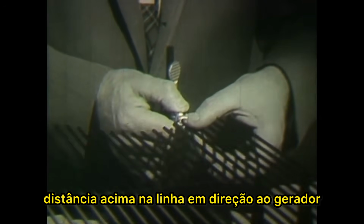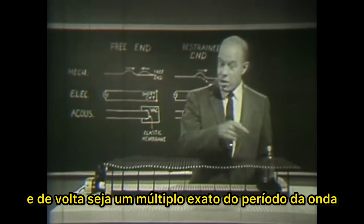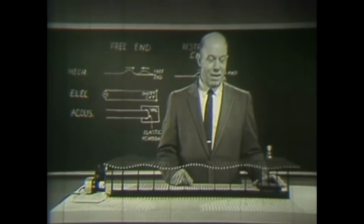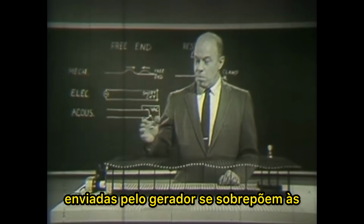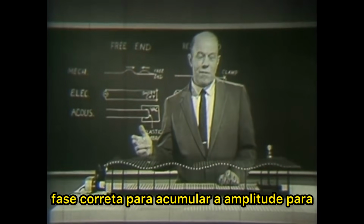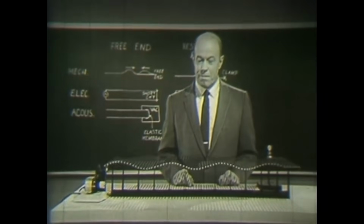Suppose I simply move this reflector a short distance up the line toward the generator, just far enough so that the travel time of a wave down and back is an exact multiple of the wave period. Under these conditions, the new waves which are continually being sent out by the generator superpose upon the previously emitted and multiply reflected waves in just the right phase to build up the amplitude to an abnormally large value, new crest on previous crest, and so on.